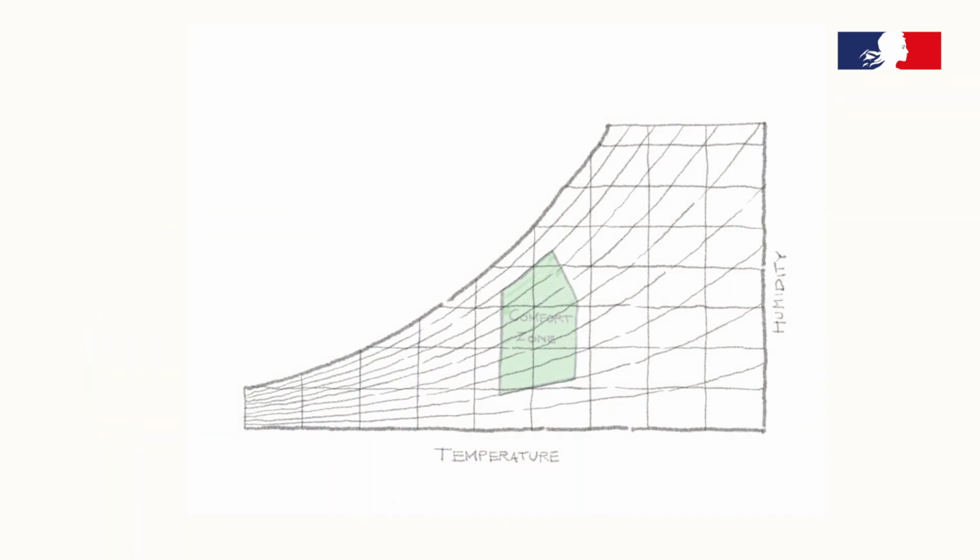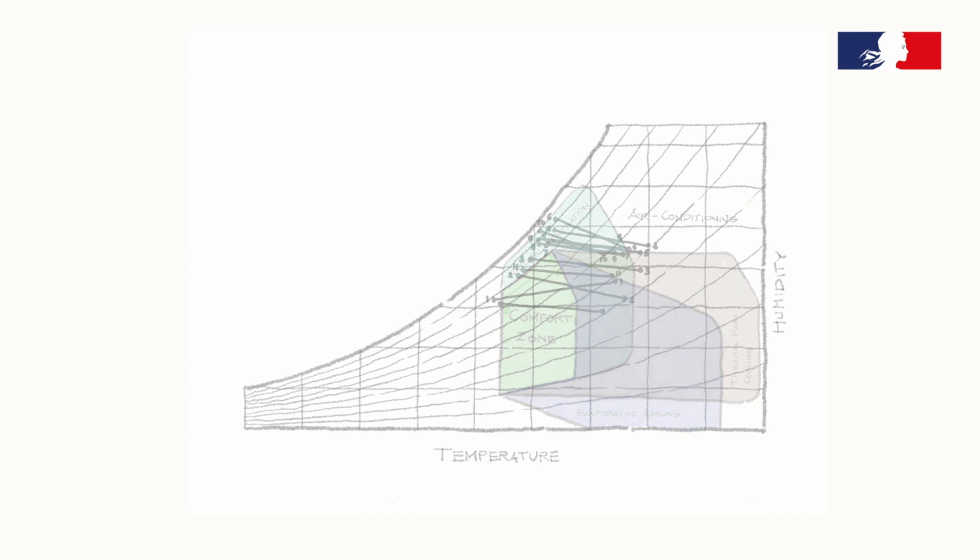Lastly, in hot and humid climates, I have taken the city of Bangkok, Thailand. This is trickier as none of the passive cooling methods can work at all times. We can analyze further, for example, into daytime and nighttime, and dry season and wet season, to select appropriate cooling methods for a certain period of time. When we cannot achieve comfort using the three methods, we would need mechanical air conditioning.